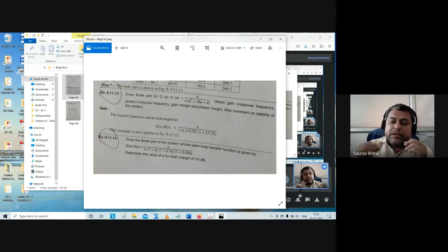You are first supposed to find the overall CS by RS, from that find the system transfer function and characteristic equation, and from that characteristic equation apply the Routh-Hurwitz criterion to find the value of K. So a big block diagram I can give you, and there I can give some value as K.